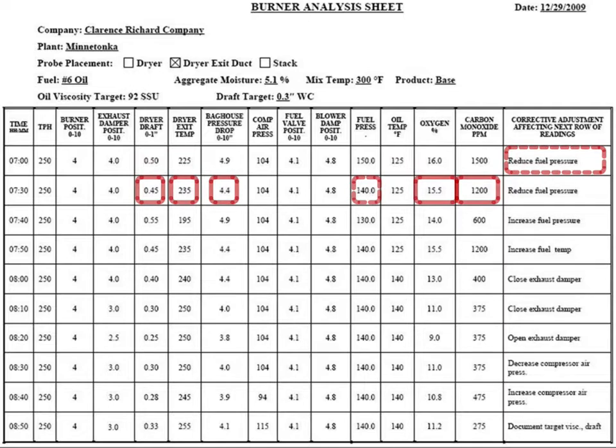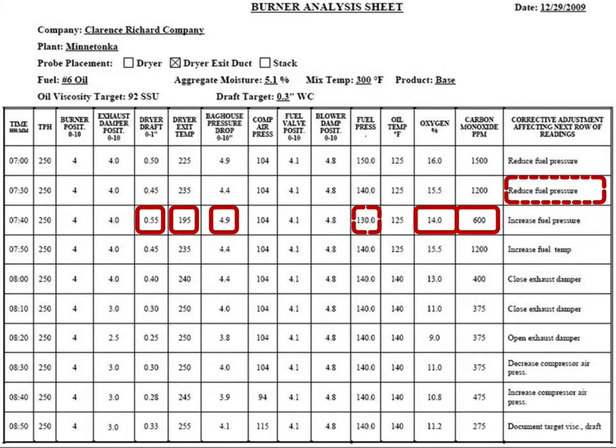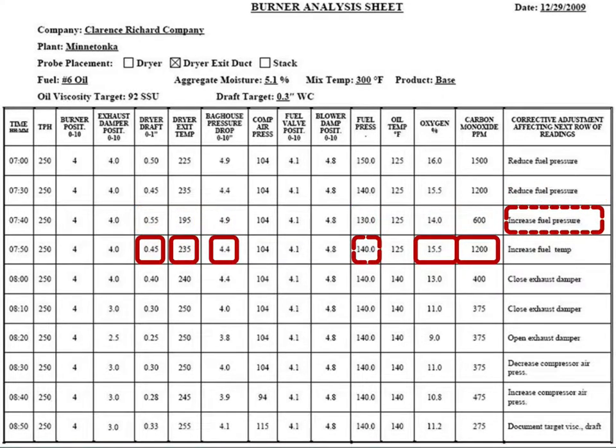This document tells quite a story when filled out. This tune-up took about 2 hours. It helps to keep variables affecting combustion consistent so as to determine if the adjustments made were correct or incorrect. Therefore, the automatic burner control and damper control were placed in manual.